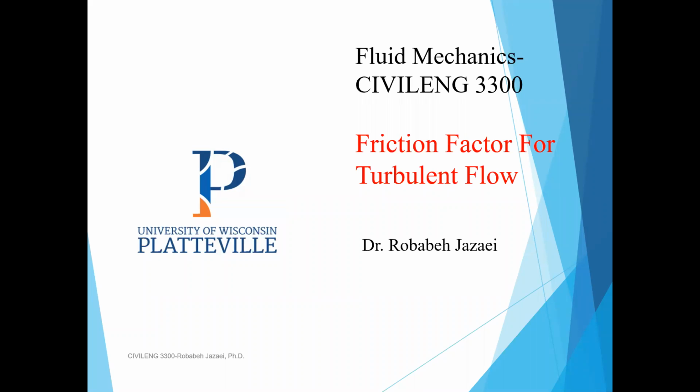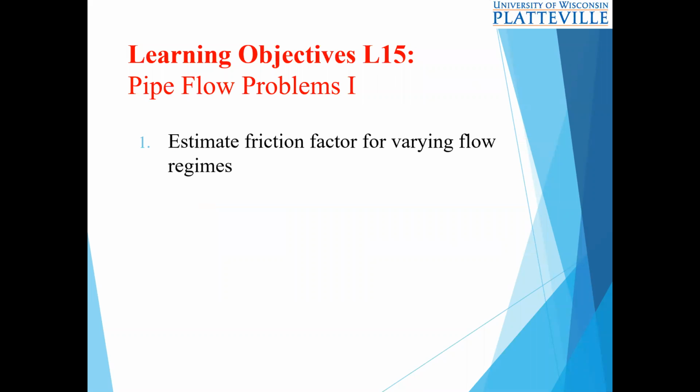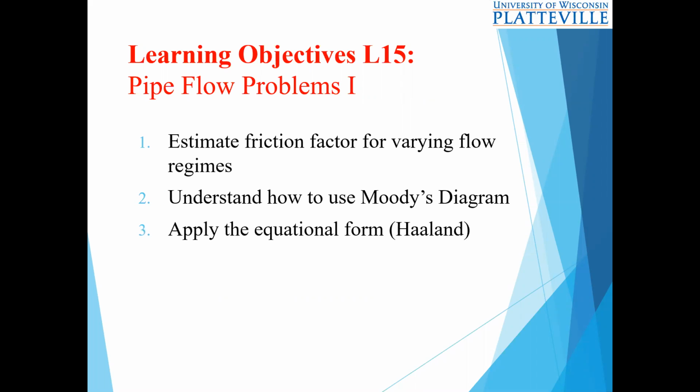Hello everyone, today we're going to talk about friction factor for turbulent flow. Let's see what the learning objectives are for today's lecture. First, we're going to estimate friction factor for varying flow regimes. And then we are going to understand how to use Moody's diagram. And third, we're going to apply the equation form for friction factor, which we call the Haaland equation.